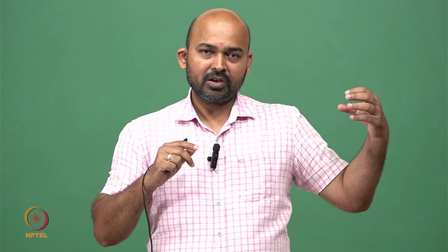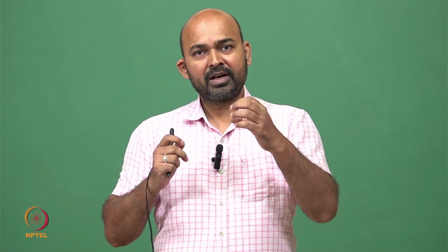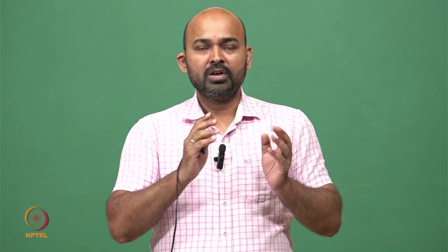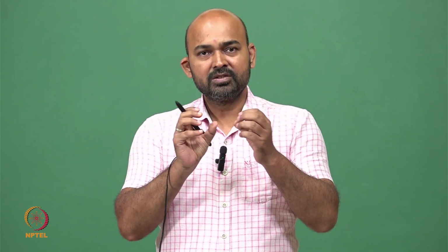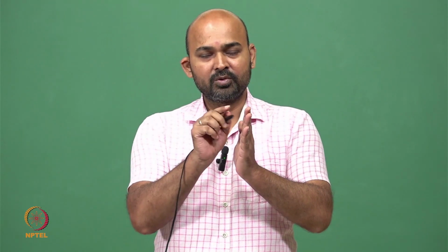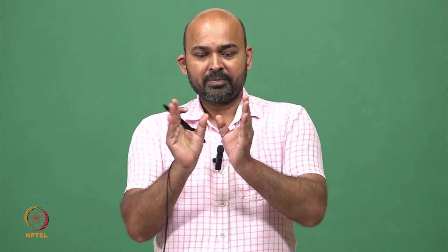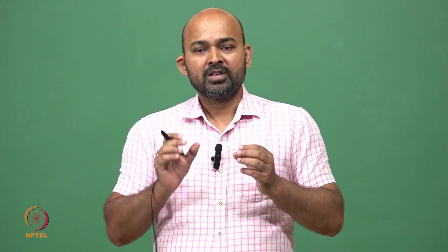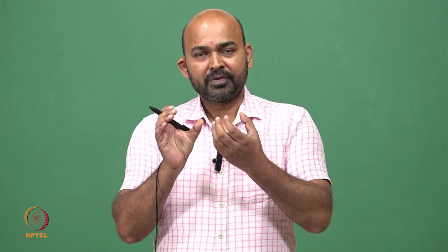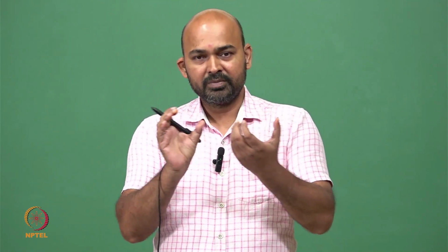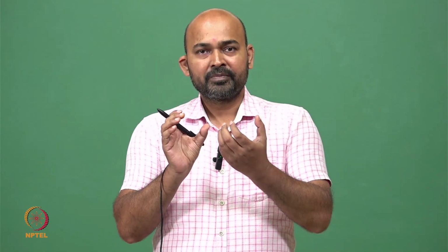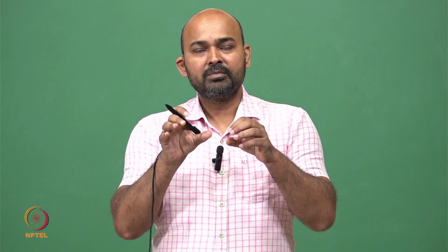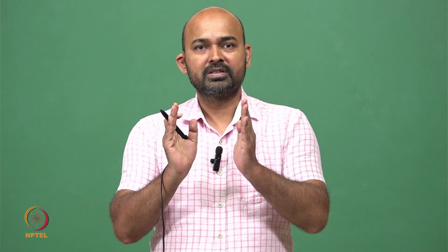So when we look at the origin, we get two waves. One is reflected at interface 1 and the second one is reflected at interface 2, and there will be a time difference between these two waves because this second wave needs to travel an extra distance of separation, which is the separation between these two discontinuities. So accordingly there will be a phase difference between these two reflected waves, and based on that phase difference we can determine the time taken by the wave in between these interfaces.